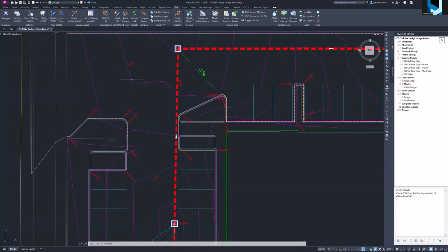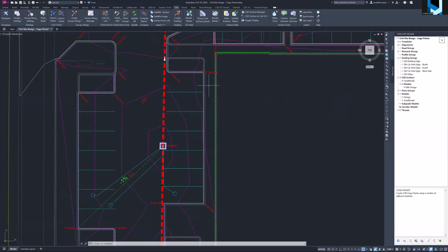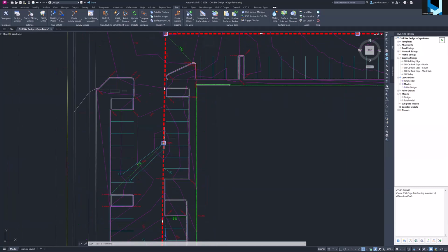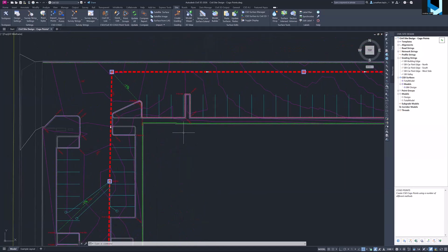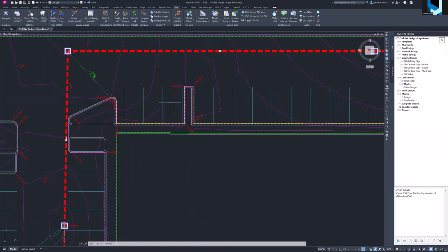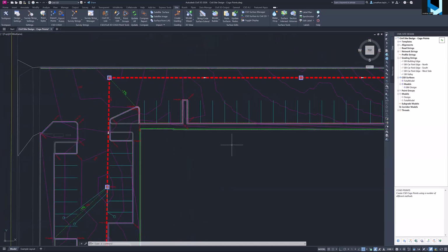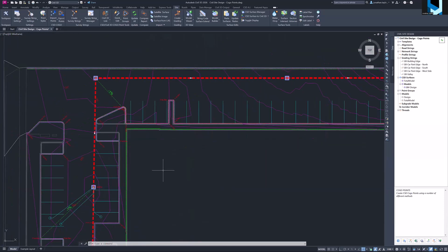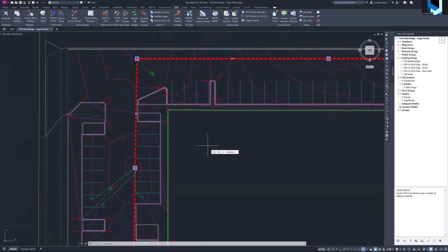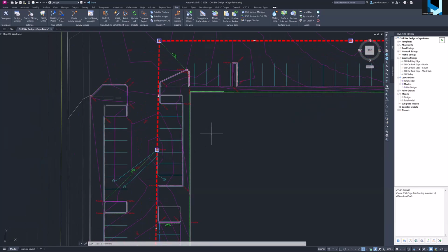You can also assign that information to your vertical design and through your strings and to your surface models, crucially. And also then use them as a kind of bookending really here to then label up your current strings using that vertical design. So there's kind of 3 focal areas: labeling, application to strings, and application to surfaces.